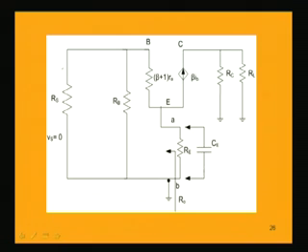The resistance across this capacitance CE can be now found out, which is say R naught, and R naught which we will be finding out across these 2 points will be in parallel with RE. RE is there, but we have to find out at these 2 points A, B, what is the resistance R naught looking from these terminals A, B, and that resistance R naught, if it is in parallel with RE, that will be the effective resistance due to CE.